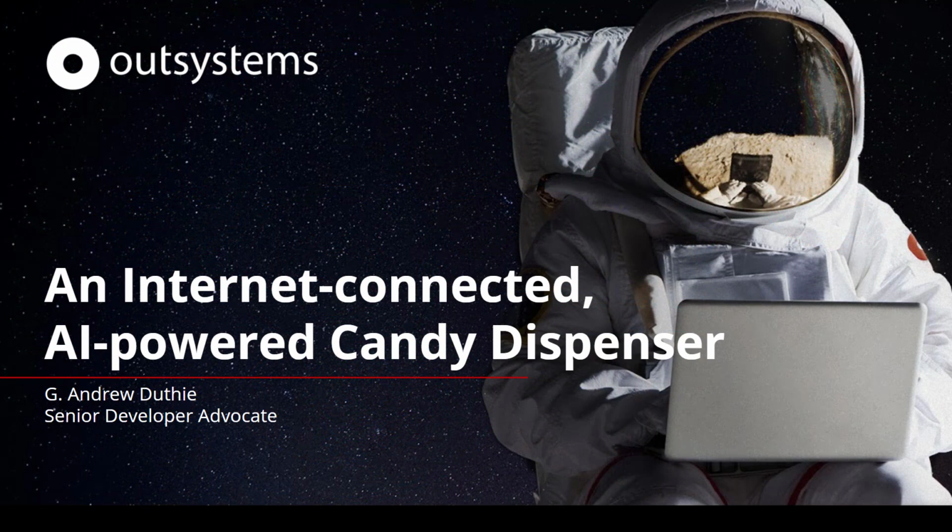Just to recap, what we saw was the use of an Arduino-programmable microcontroller board and a stepper motor to control a physical piece of hardware and dispense candy over the internet. By using a simple $20 Wi-Fi connected board, we got internet connectivity. By leveraging the programmable cloud platform that the Particle Photon provides, we are able to very easily REST enable our hardware device, and then leverage that REST connection from an OutSystems application to control the hardware from a mobile application.